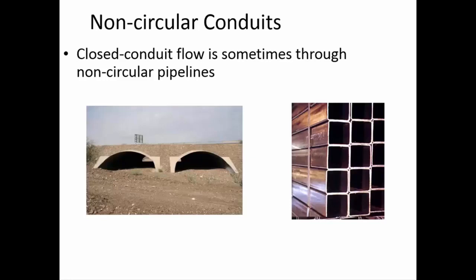And for some reasons that we talk about in hydrologic engineering, you really don't want water going over the top of the road, at least not for too long. It's okay for storm flows to overtop occasionally and for a few minutes, but if there's overtopping for too long, it could actually wash out the road entirely. And so you want to make sure that there's a big enough cross-sectional area for flow to go through.